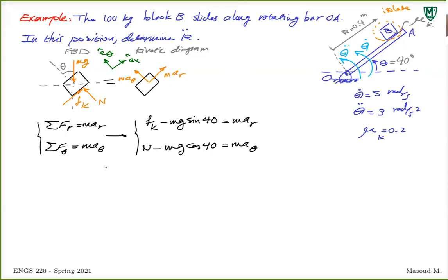So AR is equal to, well, in this case, R, I used uppercase R. So I say R double dot minus R theta dot squared. And I'll just leave it as is. And A theta, for acceleration in theta direction, you can write it as 2R dot theta dot plus R theta double dot, right? That was plus R dot theta dot plus R theta double dot.